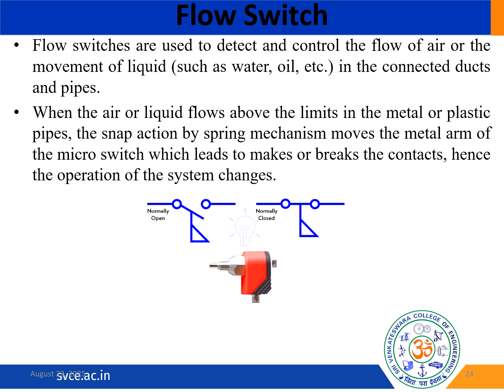This mechanical movement either makes or breaks the electrical contacts. Thereby it can alter the operational state of the connected system. For example, it can activate alarms, it can shut off pumps, or it can initiate other control responses. Considering threshold based activation, the response to flow rate is adjustable. Spring mechanisms ensure consistent actuation, which is also a reliable part in the mechanical field. Versatile installation is also possible here, as it is compatible with both metal and plastic piping.